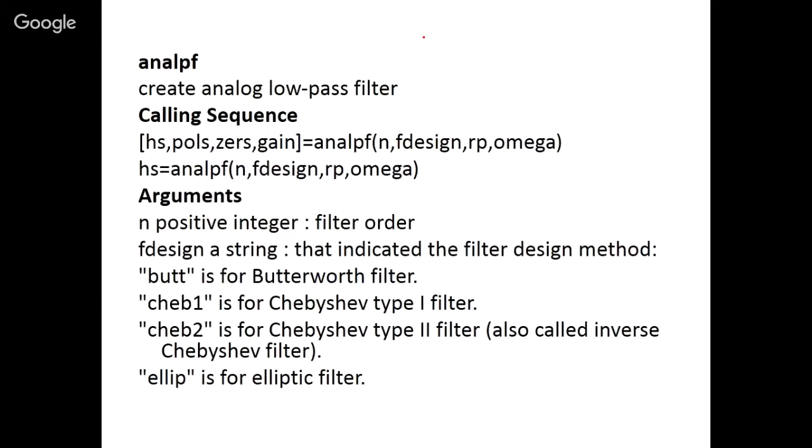In case of Butterworth, we consider that there will be no ripple, right? There will be no ripple. That means it will be simple and in a very smooth way. So this is your Butterworth filter. But if we design the Chebyshev filter, then we will get the ripple in your pass band, but there will be no ripple in case of your stop band.